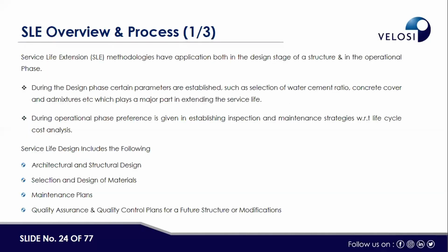So, the service life extension overview process. The service life extension methodologies have application both in the design stage of a structure or building and in the operational phase. During the design phase, certain parameters are established, such as selection of water-cement ratio, concrete cover, and admixtures, which play a major part in extending the service life. During the operation phase, preference is given to establishing inspection and maintenance strategies with respect to life cycle and cost analysis. Service life design includes the following: architectural design and structural design, selection and design of material, maintenance plan, and quality assurance and quality control plans for future structures and modifications.